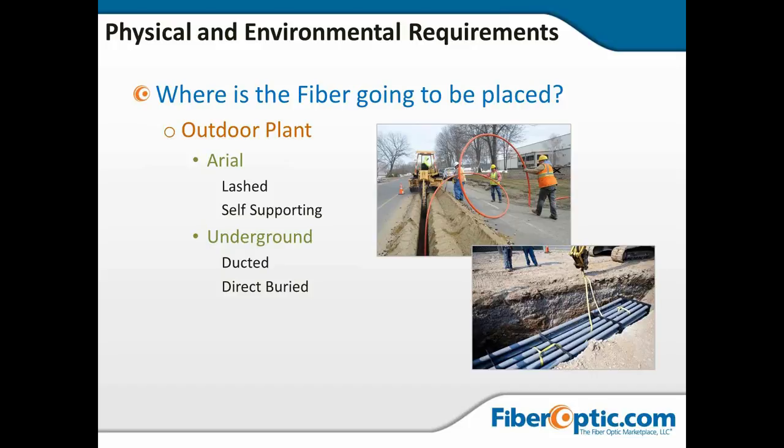And I will tell you up front, direct buried is probably my least favorite of all of these options. Too much potential for disaster, no protection for the cable. You need to spend the extra money to get armored. So all of these have to be offset against cost. And next month, when we talk about part 2, we're going to be looking at costing issues. So you'll hear that a lot of the comments that I make are going to be about cost.